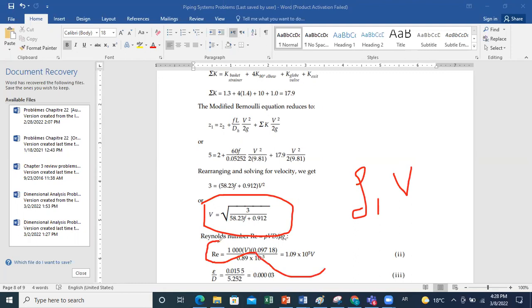So this is your second equation, and the other is the equation you got from the energy equation, equation 1. In these two equations, you already have 3 unknowns: f, v, Reynolds. So you need a third equation, or you need the Moody diagram, because the Moody diagram is like a third equation for you, and it will allow you to perform your iterations.